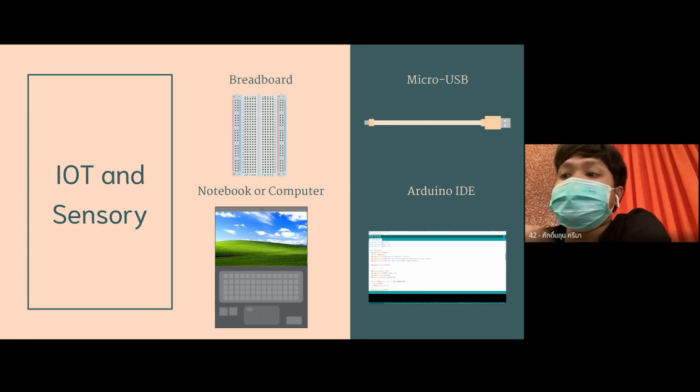For the mirror, step 1, place the NodeMCU on the breadboard. The rest of the instructions assume the front of the PM2.5 sensor is facing you. Step 2, connect the jumper wire to the PM2.5 sensor.